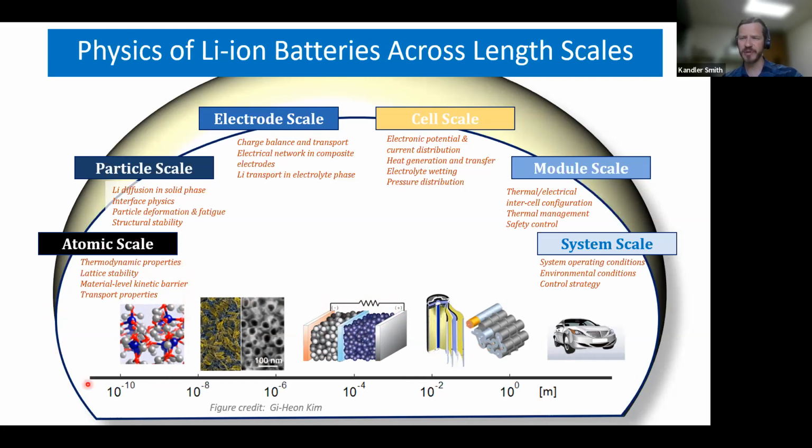To a certain extent, you can predict some reaction and transport properties that feed up into these continuum scale models. Our group works mostly at the continuum scale, where we predict how the lithium moves around within individual active material particles and the composite electrode, and how that contributes to the overall battery's performance.